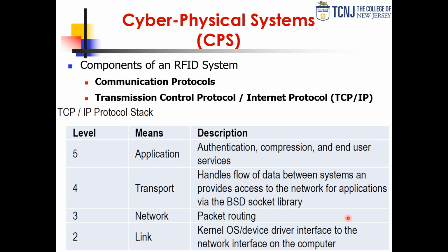But once you are in that link layer for TCP/IP, you have the link layer that serves the operating system device driver interface to the actual physical layer through the MII or RMII. So the driver in the data link layer is the one that talks to and manages that interface.